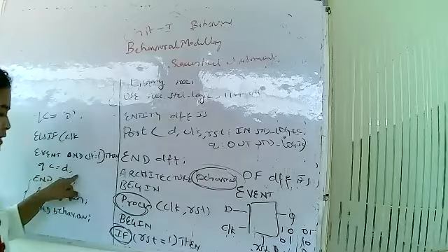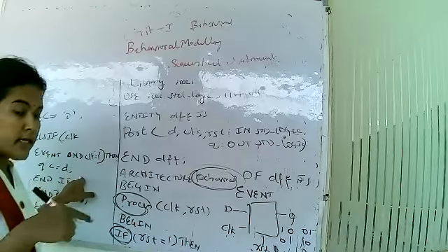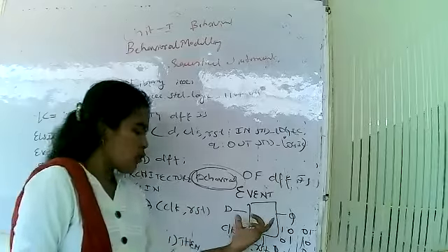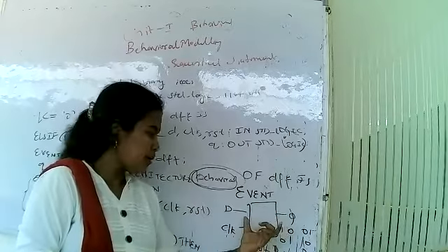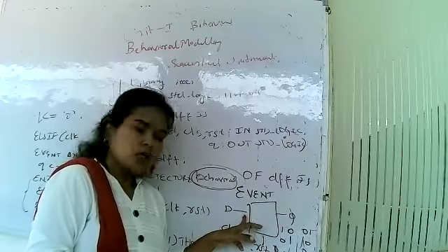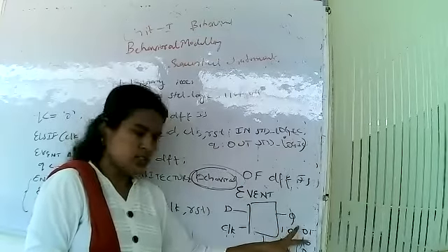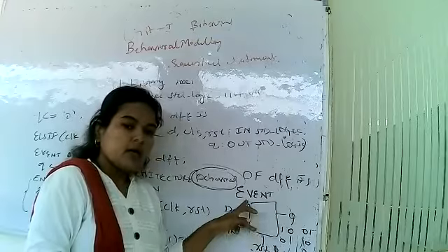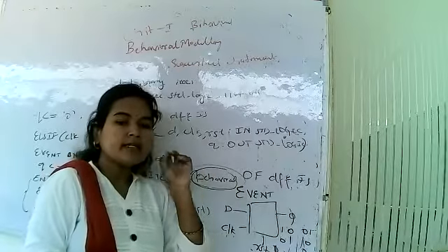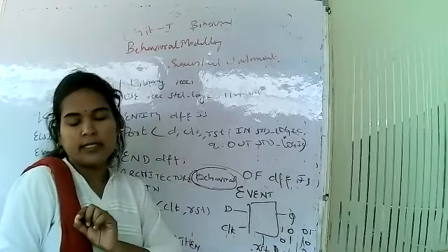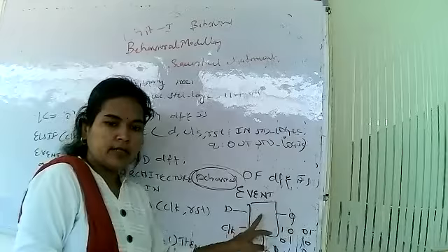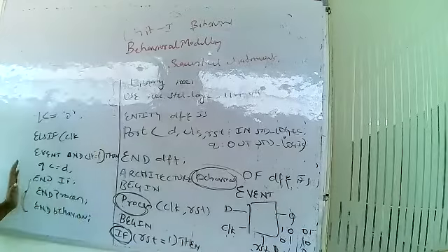When clock is 1, output acts as a memory, that is, whatever is the input, that will be the output. At the D, what is that? It is a single memory element. If clock is 0, output is 0. If clock is 1, whichever data is present at D now, that will come to the output. It is just a memory element, it will not process anything. So only if clock is 1, output will be D. If clock is 0, output will be 0. That is there in this.